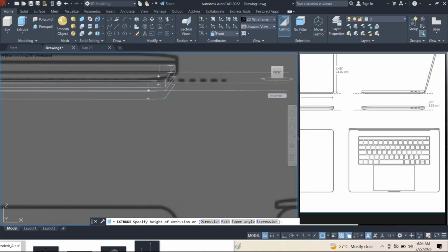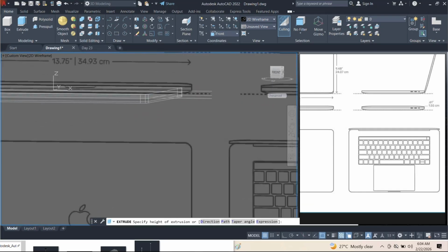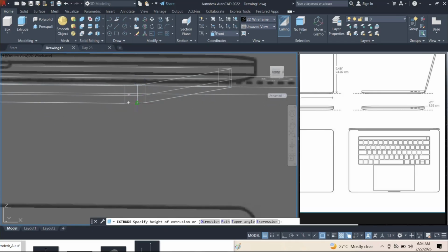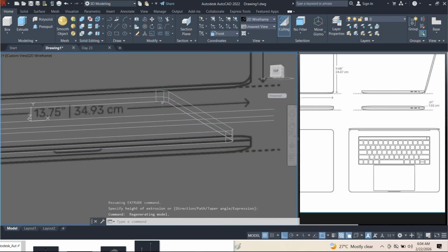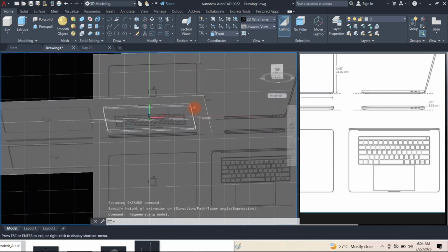So we're starting from here, so we can bring it here or here. It doesn't really matter which one I want. But then if I now do the extrusion like so, I'll now start filleting this edge. So that is one way I can approach that.